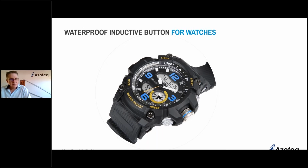And the buttons are often the first place where the water gets in, either due to aging or pressure-related issues. So once again, with the hermetically sealed housing, you overcome a lot of design constraints, you simplify the construction, and the simplified construction means a lower assembly cost and a higher reliability.